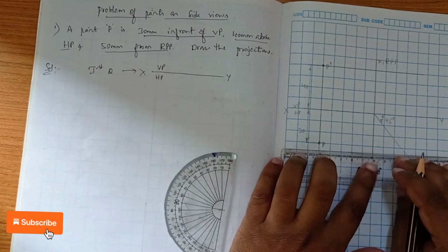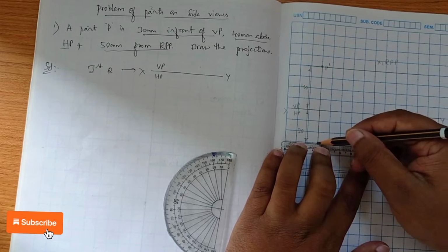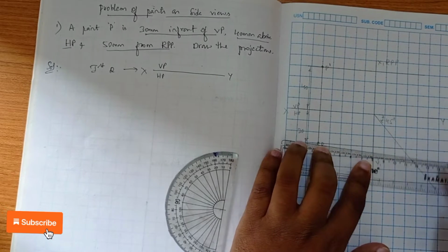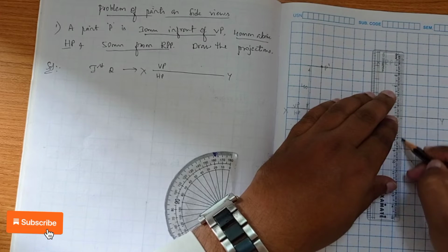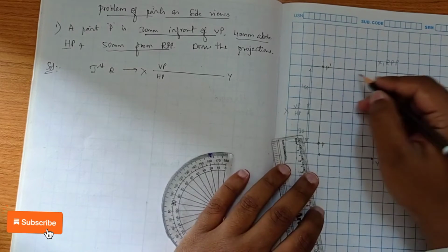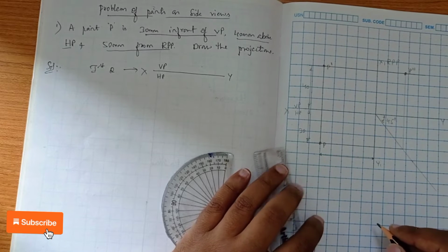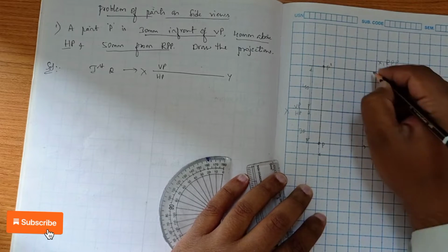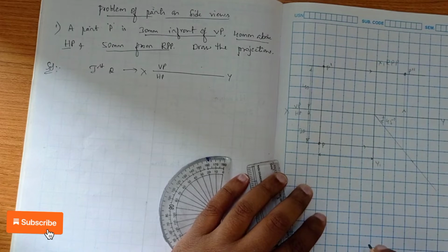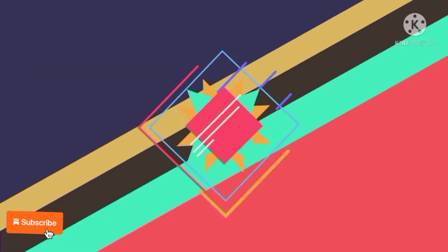Now from the top view we draw a straight line until it touches the 45-degree line, then we project upward. Where these two lines intersect, that point is our side view. We can show the direction of the projection line. So this is the side view.